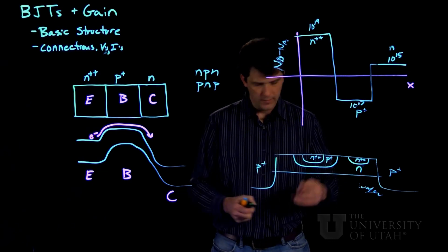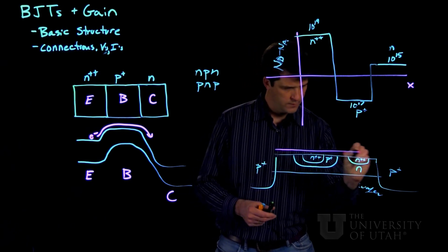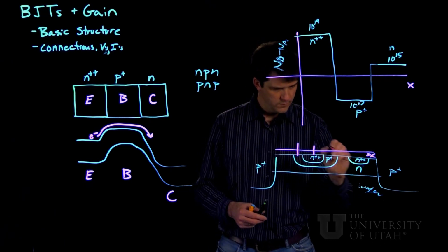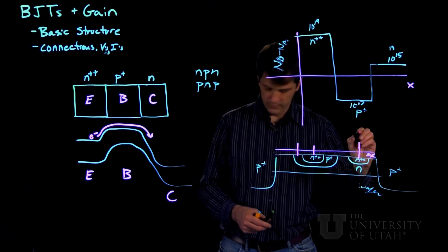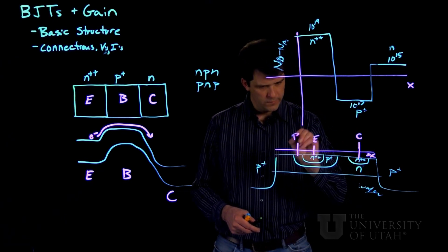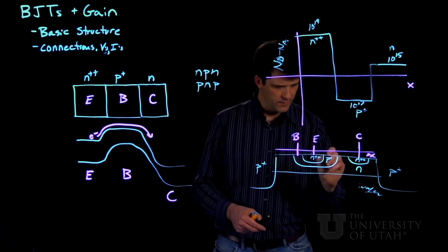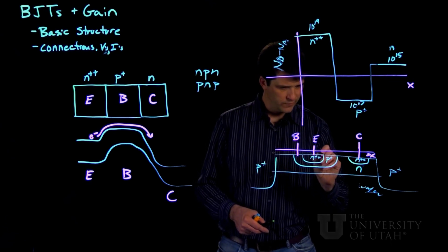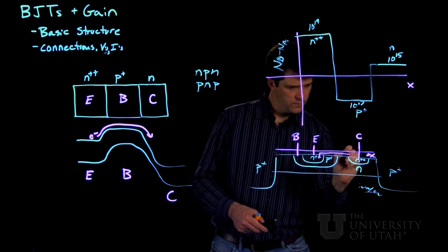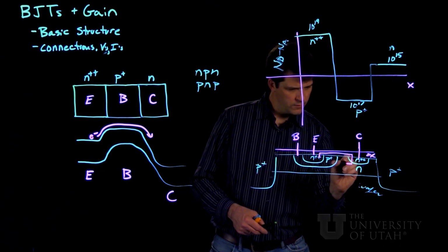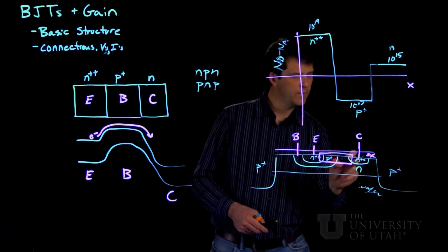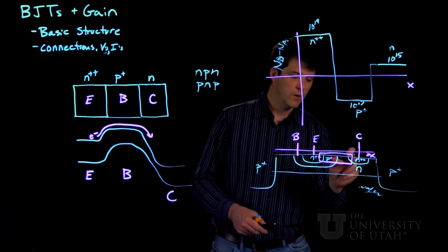And then we would have oxide over everything here. And we have to figure out what our wires are. So this is the collector, this is the emitter, and this one here is actually the base, but electrically, it's connected to this P plus region, so that the order, if we look from here to here, is N plus P plus N, and then N plus again for making the ohmic contact.